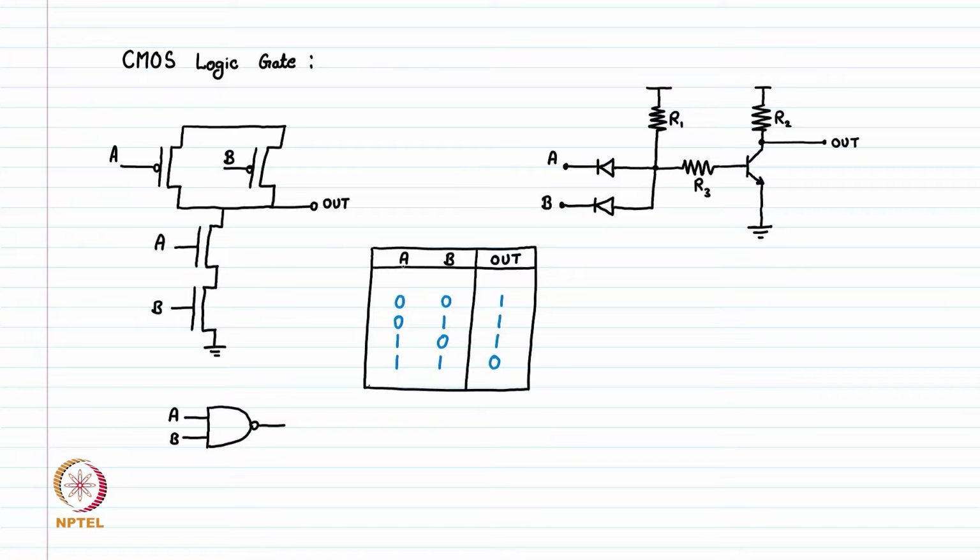Let's say both the inputs A and B are 0. Because this intermediate point, let's call it X, the node X is actually fed high through this VDD. And signals A and B are connected to ground, which is the first line. That time the diode will be turning on because this side is high and this side is low. So the diode will be drawing power and pull this node X to ground, which is low.